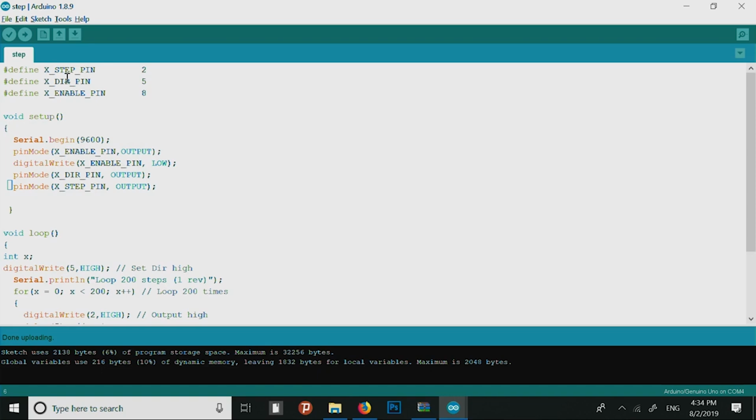There are a lot of other motor drivers also. This A4988 has a current carrying capacity of around 1.8 amperes. So, if you are going for a higher power stepper motor, you can use some other motor drivers. There will be plenty of heat generated when we use these stepper motor drivers, and every one of them will have a heat sink to transfer this heat into the air.